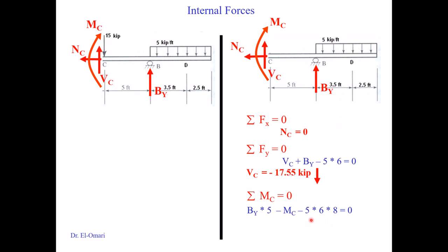So you have 5 times 6, the base, times the distance 8, which is acting exactly at half the distance, and then add to that 3, add to that 5 is 8. This will give us also a negative 225 pound-foot, which means it has to be rotating clockwise, or the opposite to the assumption. For this case, there will be no change in the x direction.